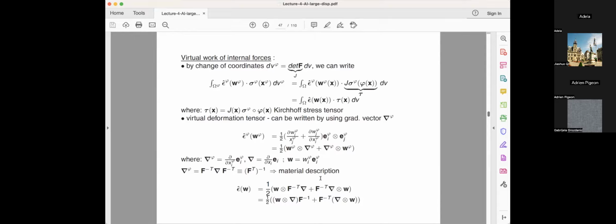So you can see that large deformation is all about applying the same principle that you already have with small deformation, plus the transformation that takes you from the deformed to the initial configuration, or whatever, forward or back. Often in the terminology of the manifold book by Marsden and Hughes, it's called push forward and pull back and so on and so forth. And basically this is just the transformation, nothing else. So let's go back to the internal work.